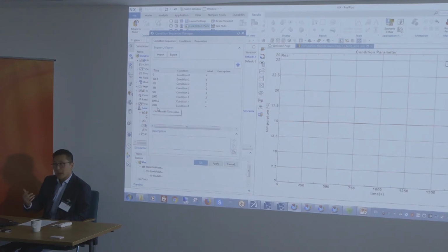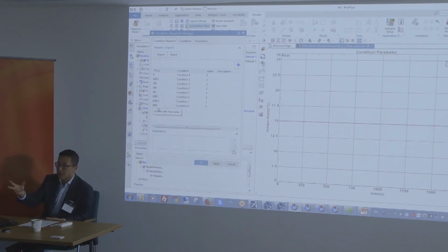I think you could use it, but I think there's maybe an approach that might be better. Right now, in a solver, there's the option of stopping the analysis whenever you reach a particular thermal condition. So let's say you reach that condition where your phase change starts or ends. You can stop the analysis and save the results. And then from there, you can rerun an analysis very easily by using those results as a baseline. But I think the key here that's in the platform right now is a stopping condition based on a particular criteria.